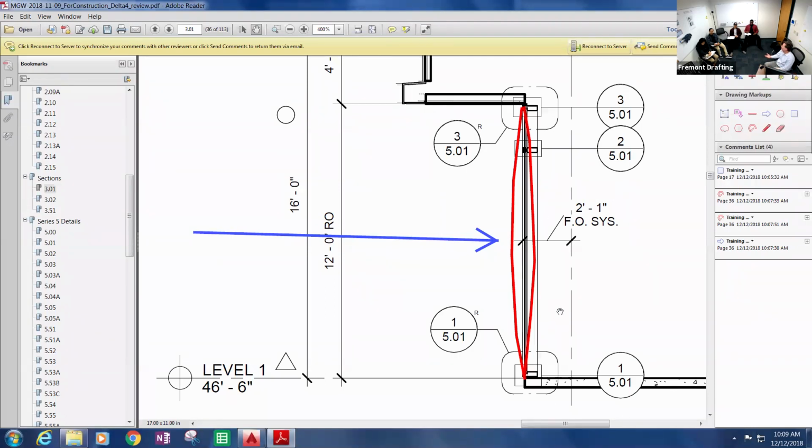And so we see that a lot in our curtain walls now too, where the architects are wanting larger and larger areas of vision glass. And so that comes into play there, just ensuring that we're not over deflecting on the glass. And in reality, the glass manufacturers can sometimes go over that 3/4 of an inch if you ask them, and it gets sort of special dispensation or whatever. That's just sort of their industry's general rule of thumb from the glass manufacturers. The specific glass manufacturers, if you ask, we can sometimes go over that.